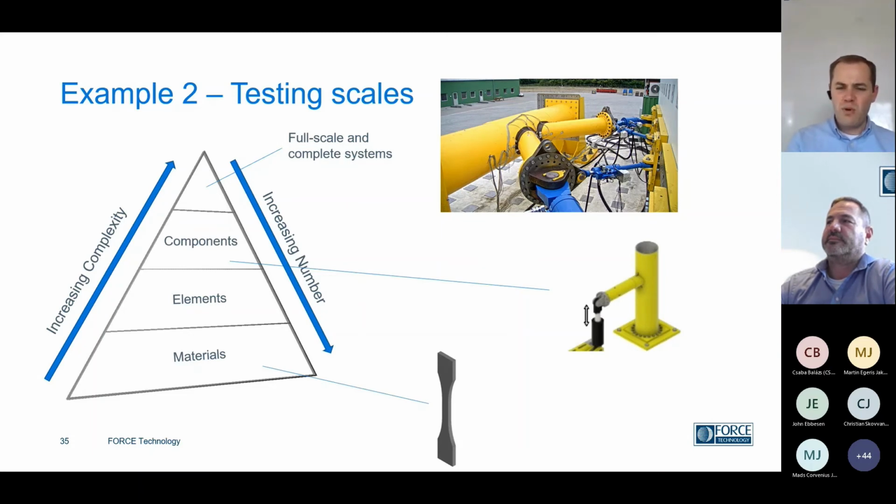And in this test program, where we were testing the welds between the brace, the small pipes, and the big pipe, we were going to fatigue failure, with a full through thickness crack defined as failure. So we had to grow that crack. It ended up initiating in the big pipe, in the chord. So we had to grow it full through thickness of the 60 millimeter material. That was one of the crack cross sections that you saw from Rian earlier in the presentation.